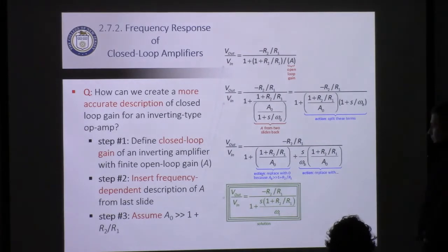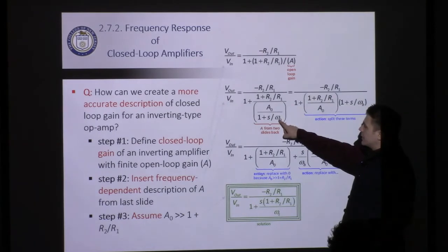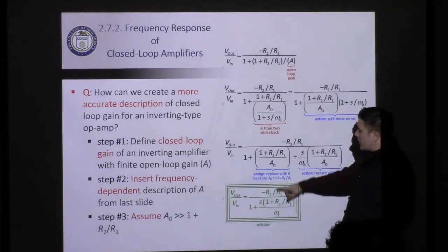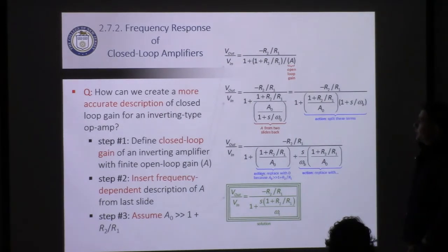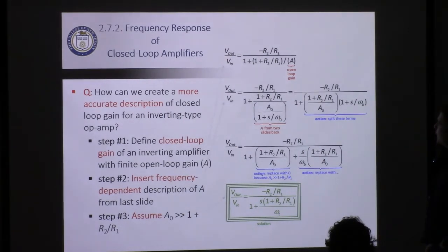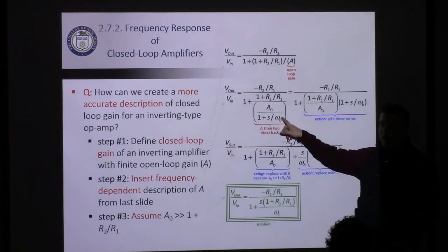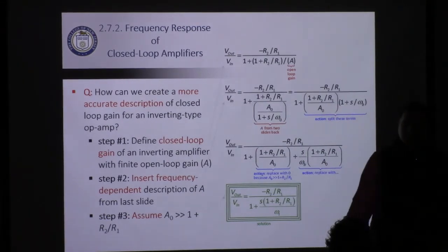Now, this is just one version of the equation you can make. You can see that by changing around the math, you could also derive a version of this which was dependent on the corner frequency. So it would look slightly different. You could also define it in those terms. Just note that there's some terminology back and forth here. We use omega b and omega naught as the same value, corner frequency or break frequency. They're the same thing.